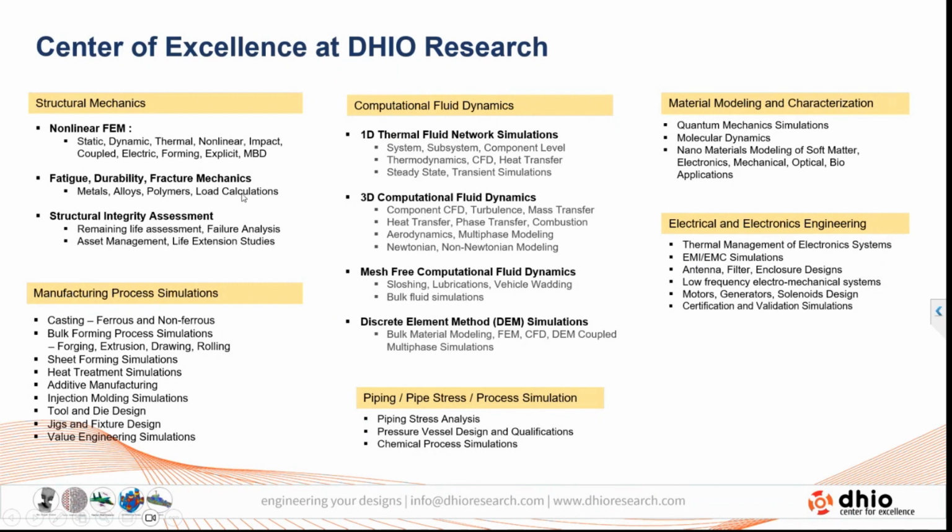And in situ load measurement, because for standard equipment and standard operations, you will get the load from the standard handbook or the measured part. But when it comes to off-road kinds of vehicles, the load becomes very critical, or developing a duty cycle which is required for the metal fatigue evaluation, followed by a fracture mechanics part.